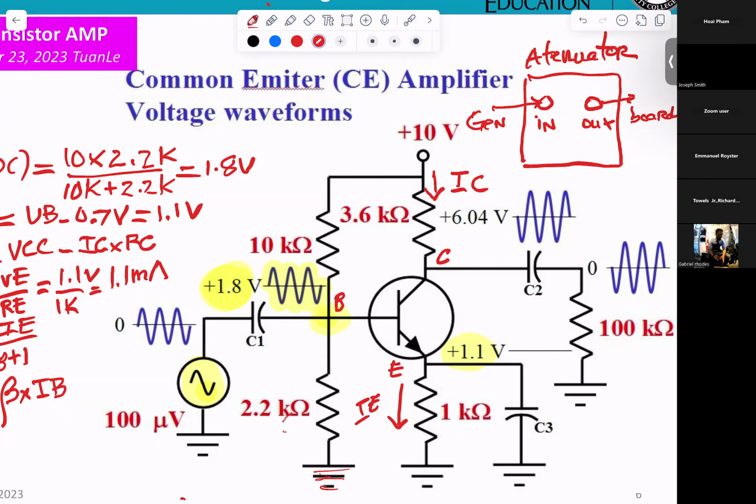You're talking about the lab board that deals with the attenuator and how to adjust it on the input. Right. You connect the generator output to the input of the attenuator, and the output of the attenuator connects to your circuit. And you can adjust the attenuator, just a voltage divider inside. So this can be any voltage you want. This is on the lab board, not on the oscilloscope or the generator, correct? Right.